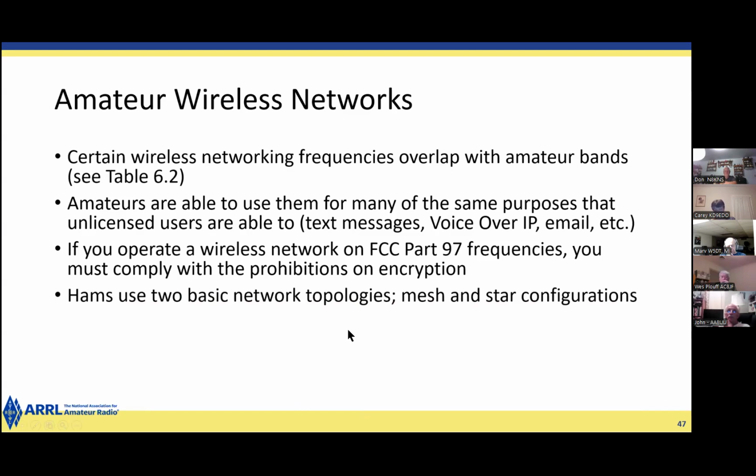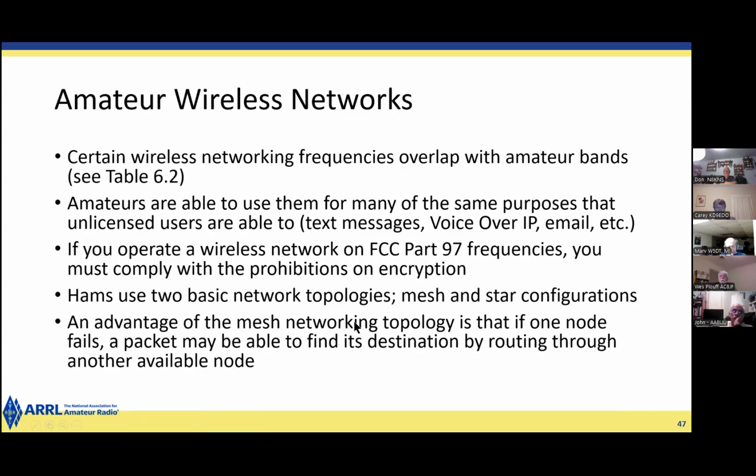So we use radio networks that have the same layout or topology as ordinary wireless networks and wired networks, like in an office building. Mesh and star. Star means that there is a router or some master node at the center of everything, and communication radiates out to end nodes. Mesh networking means that messages are passed from node to node to node, and is not necessarily very organized.